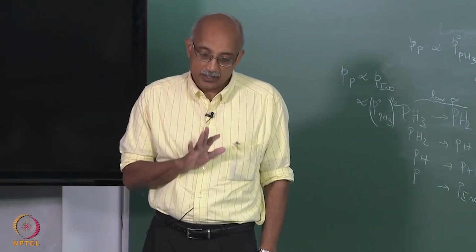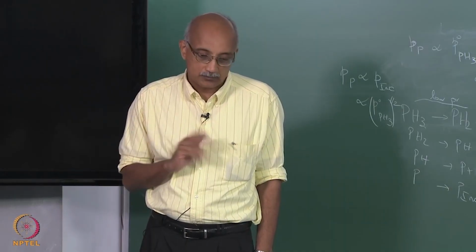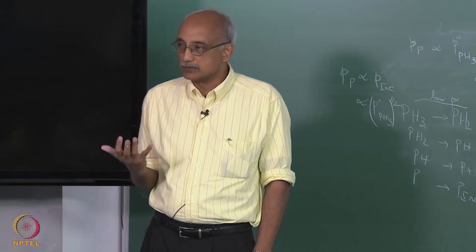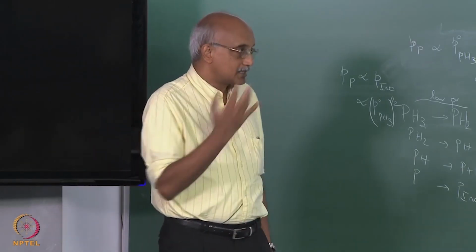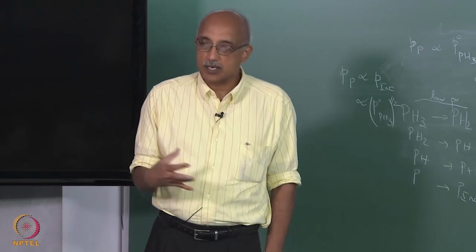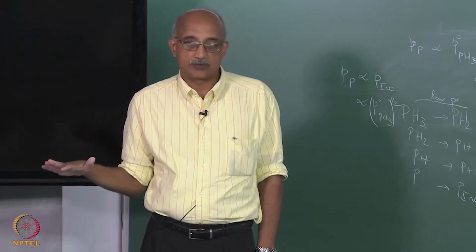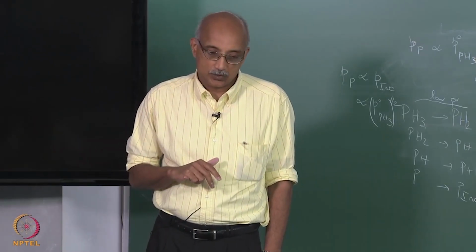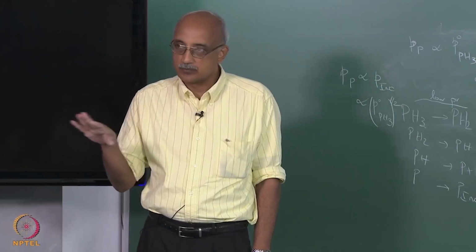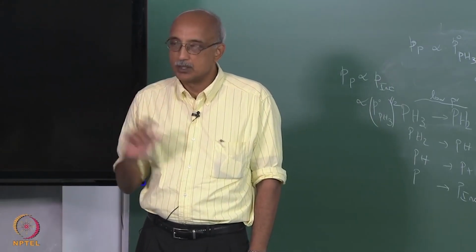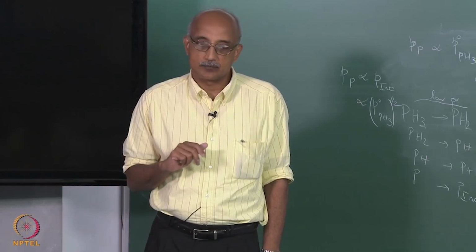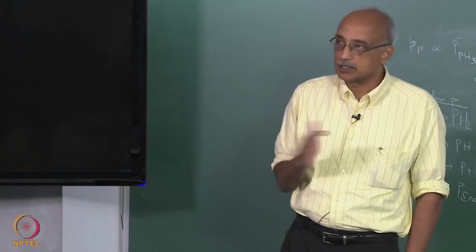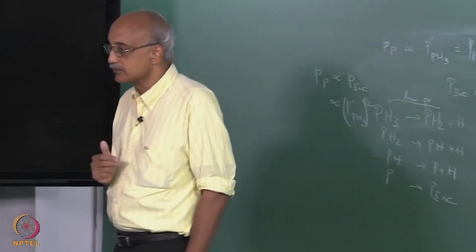And by the way, the CVD reactor is considered to be the most convenient way to incorporate dopants, because as long as they are vaporizable, it is very easy to mix them in with the CVD reactants and have the deposition of the dopant happen concurrently with the deposition of the CVD film. And so, you get a fairly uniform distribution of dopant material in the CVD film, which is a huge advantage, because there is virtually no other doping method that can really get you that type of characteristic.